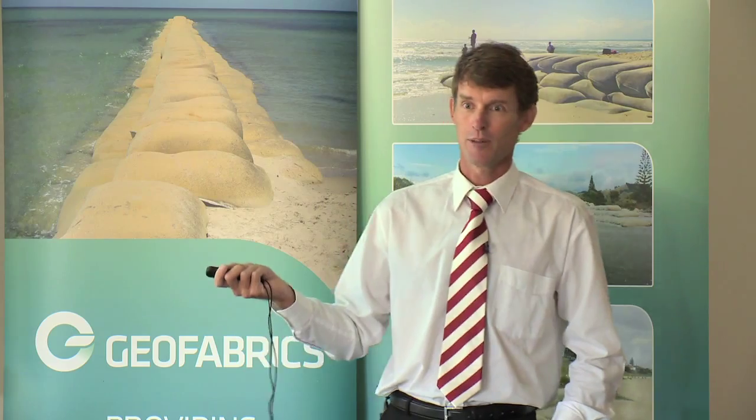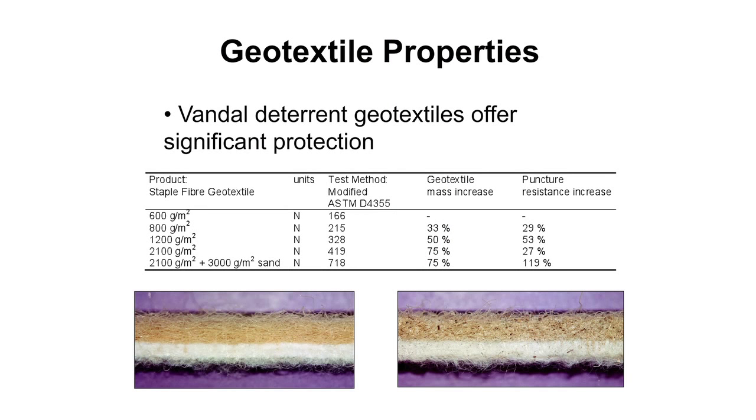We also did some testing where we showed in the laboratory, where we used a sharpened instrument, that by increasing the mass of the geotextile, that base layer, we get better puncture resistance. But it follows pretty much a straight line. As you increase the mass, the puncture resistance improves.